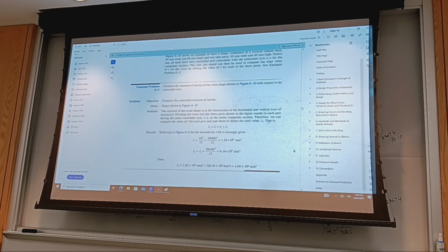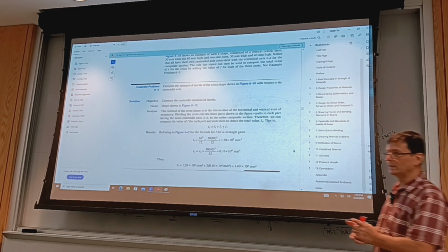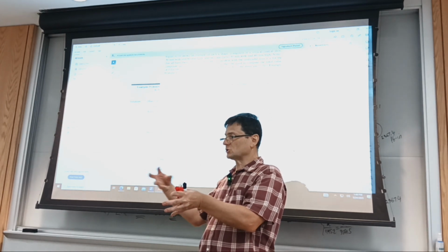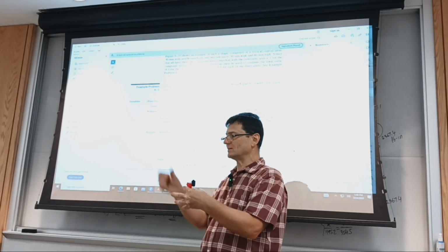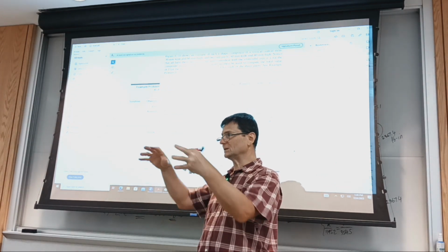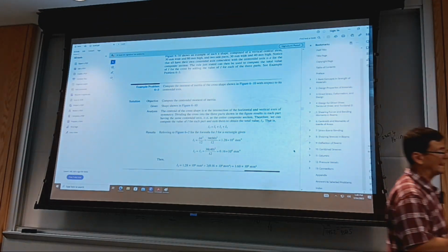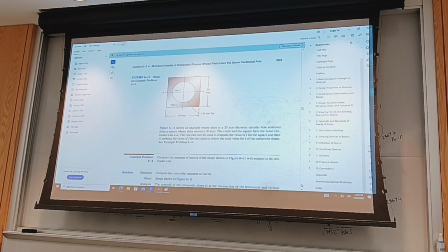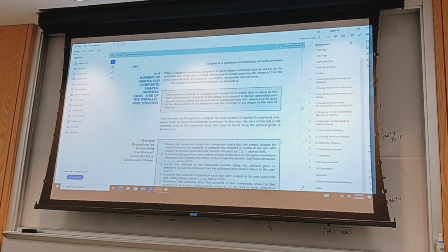That integral will come up as we do moment equilibrium of pieces of beam, where you have stresses acting on both sides, and they are holding each other in equilibrium together with the reaction inside of the beam at that location. It is needed to find the area moment of inertia for calculations with beams, stress analysis of beams.